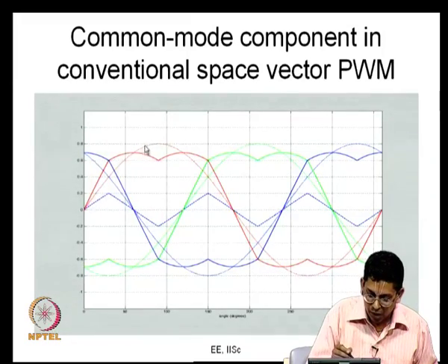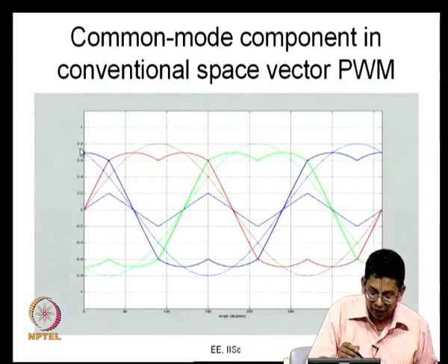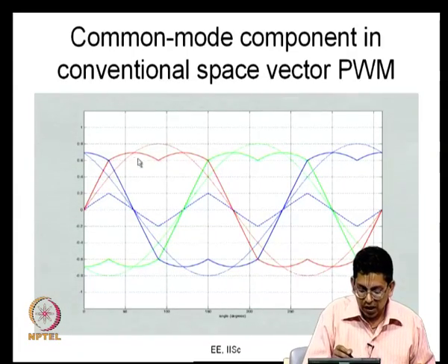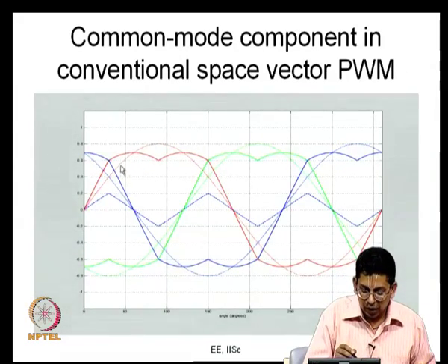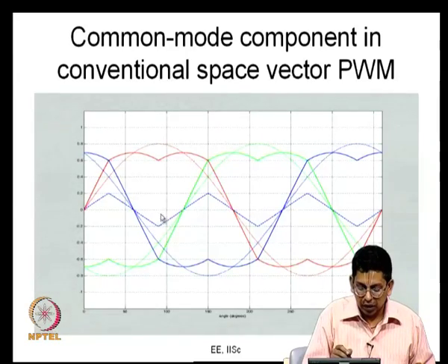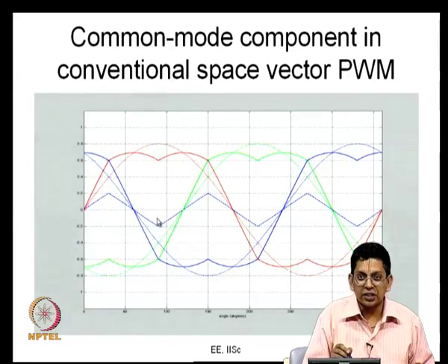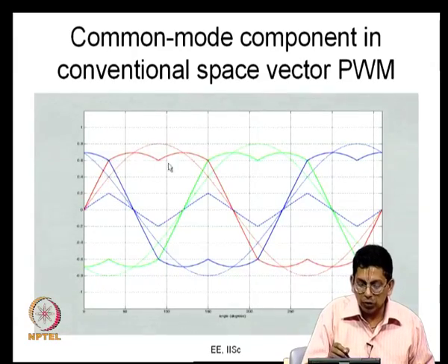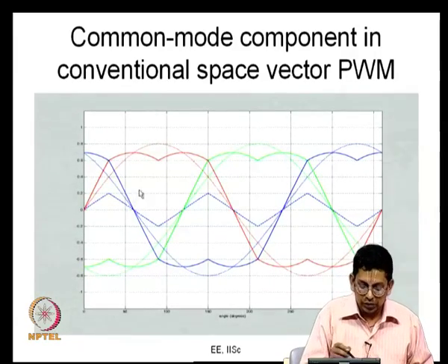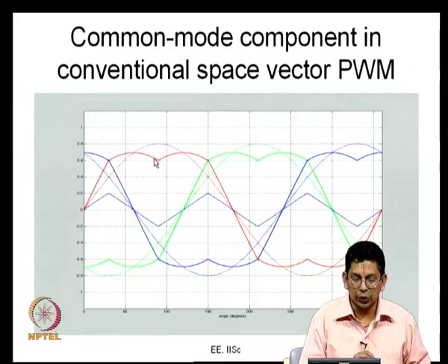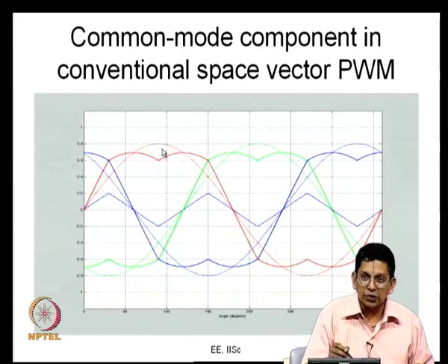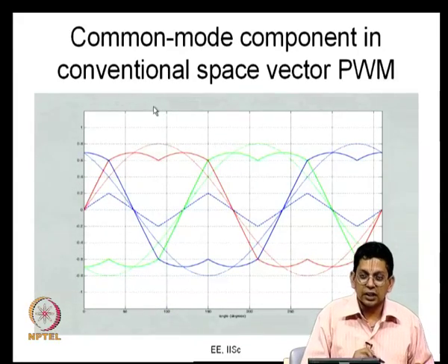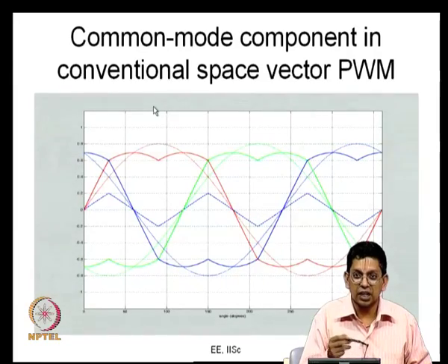You see this is your MR and it has some peak, and I have taken it as 0.8, though it is not very clearly readable here. And MR star has a lower peak value, because whenever MR is going close to its peak, the corresponding common mode voltage is negative, and therefore, it brings down the value of MR star. So, this value is lower. So, what can you do? It gives you the possibility of making this original sine waveform's peak greater than that of the triangular peak, just as we did in third harmonic injection.